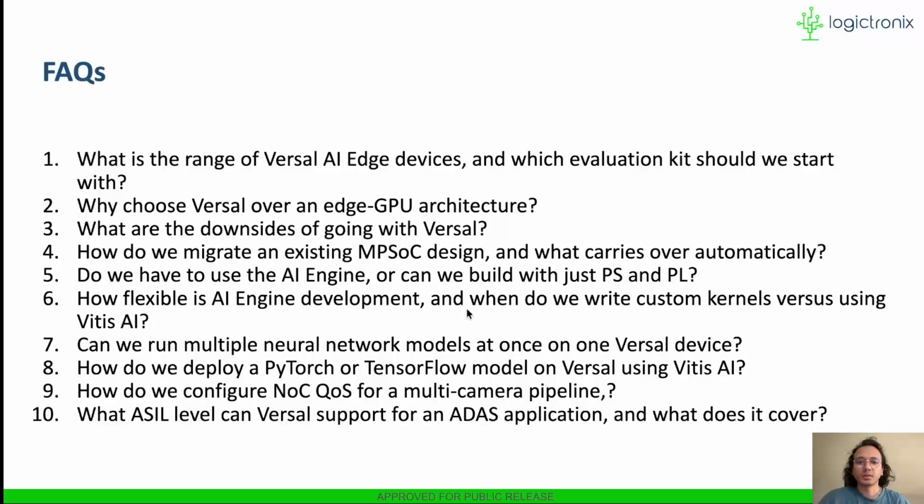One of the best approaches will be to start a project from scratch targeted for the Versal devices, and take the components for the PL logic as it is, but also we need to re-architect the system for the routing to go through the NoC instead of the AXI interconnect. So we might need to redesign and restructure the whole MPSoC based system.